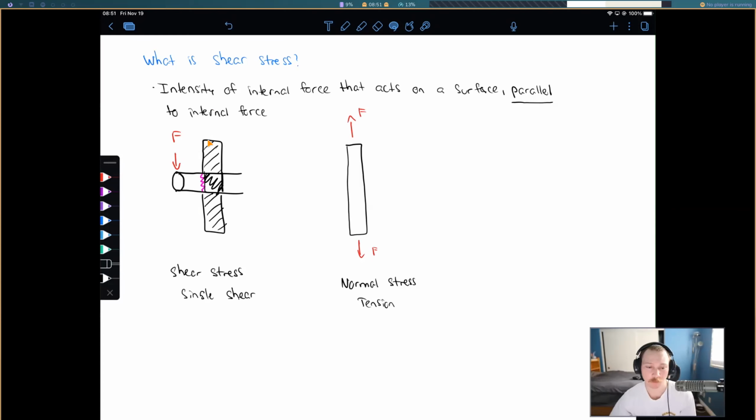Okay, and what we're going to see, well, in this case, we're looking at single shear here. So you can imagine that we're applying this force downward, and eventually it's going to fail from that shear force, and it's going to shear off right where we have this labeled in pink here. So it's going to kind of cut right there, and this is going to be that shear surface that we have. So it's failing in this one location. We're going to separate into these 2 different pieces here. So this will be one piece, and then this will be our other piece.